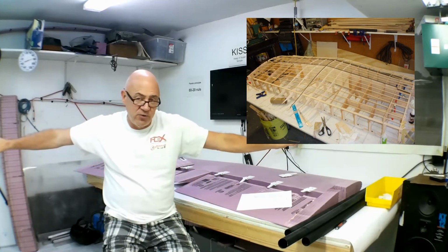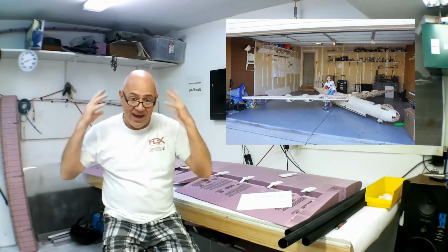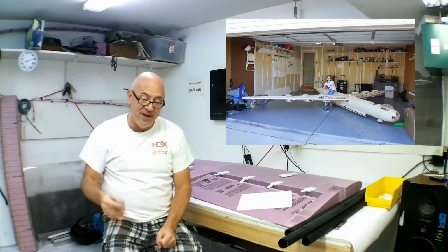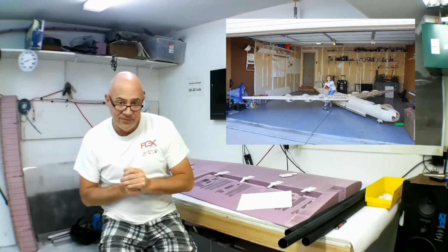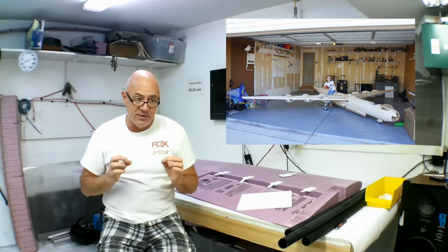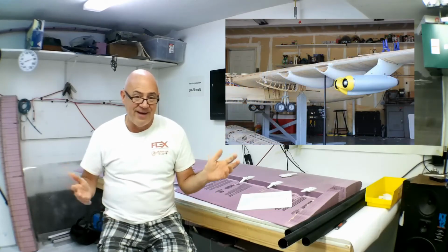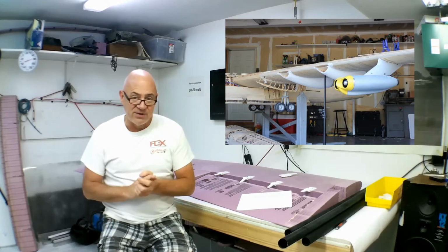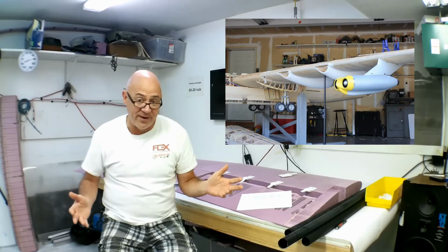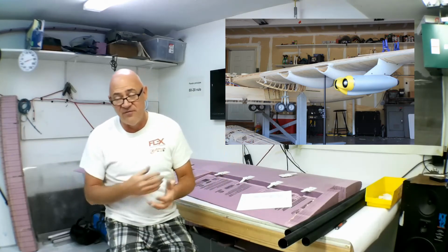So it would actually want to lift up off the balsa wood a little bit. So that 21.5 foot wingspan airplane, the wings sagged quite a bit. And I'm like, how can that happen with the carbon fiber? I never thought about compression. Stupid me should have built spruce spars in there, added the 8 ounces of weight, and just called it a day on a 112-pound airplane.